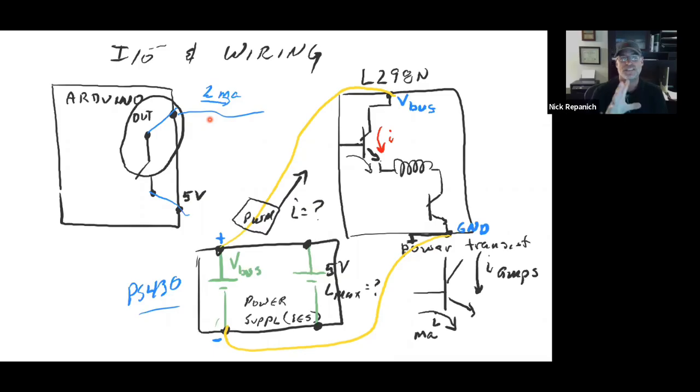When you disconnect it, that back voltage blows up whatever it's attached to, depending on which wire comes off. So you have to be really careful with inductive loads, because that changing field goes poof, and once you blow something up you can't unblow it. And the worst part is you only had one.